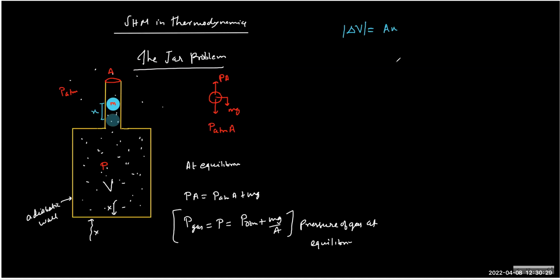If I push the pebble below, the gas pressure will increase, yes or no? Yes, it increases. So if the gas pressure increases, then it will act as the restoring pressure, right? Now we are dealing with the restoring pressure, which is developed due to the compression of the gas. Do you realize this? Understood. Now, this is an adiabatic process, because heat exchange is not possible.